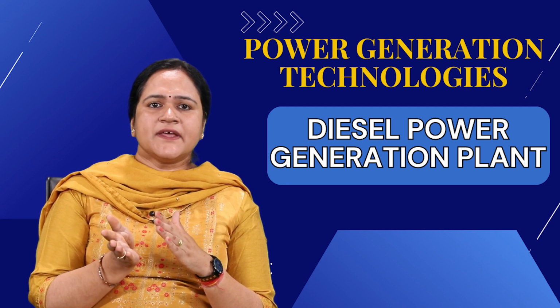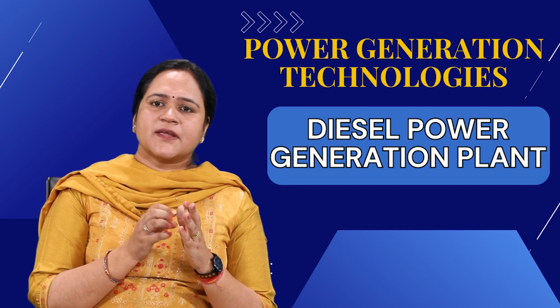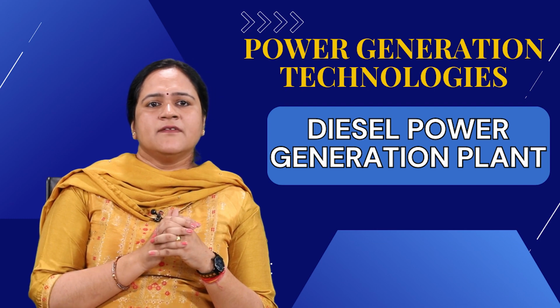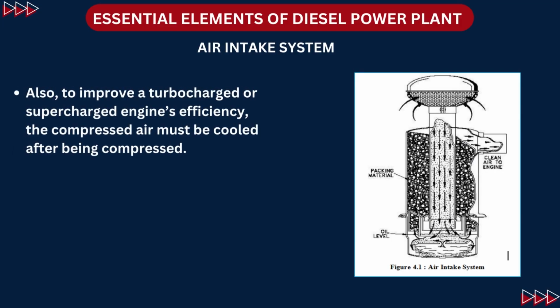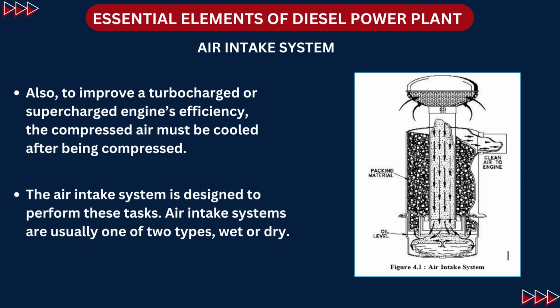If we are circulating exhaust gas, then also there is a cutoff so that the temperature of the air should not be too high. Then, to improve a turbocharged or supercharged engine's efficiency, the compressed air must be cooled after being compressed. So the air intake system is designed to perform these tasks, and this air intake system is generally of two types, wet or dry.